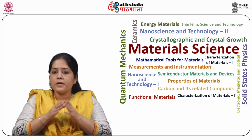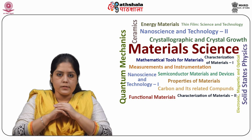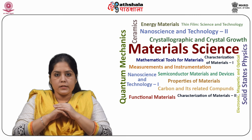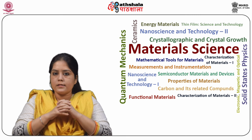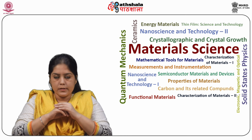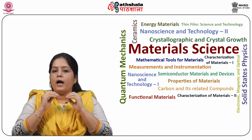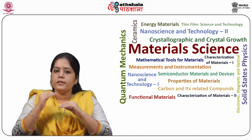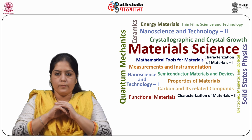So, the elastic properties of such hybrid composites can be predicted using the mechanics which we have discussed earlier, using the mixture rule, that is E is equal to the summation over i equal to 1 to n of Ei multiplied by Vi.